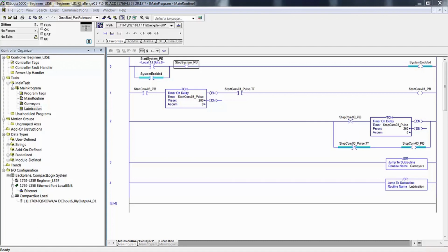Obviously you can see the advantage of retroreflective in that the photo eye, which has a transmitter receiver, has a cable on it, and it electrically has to be routed back to the controller. Where the reflector, it's just a physical object attached at the right point, and you have a bracket so it's adjustable so you can move the reflector to the position that you want.